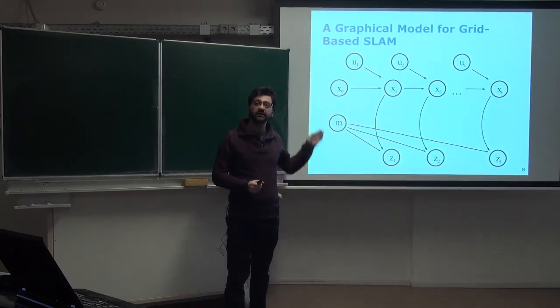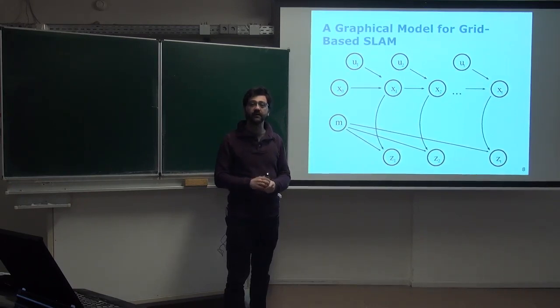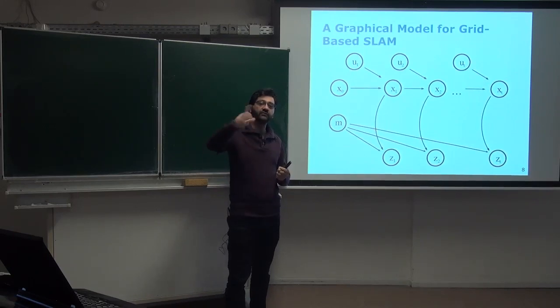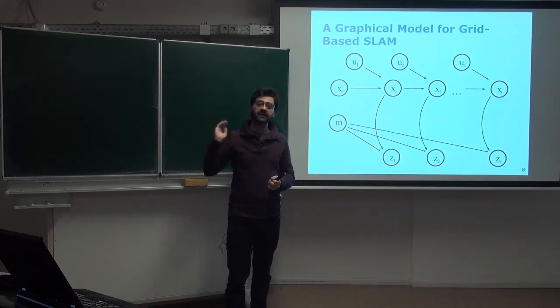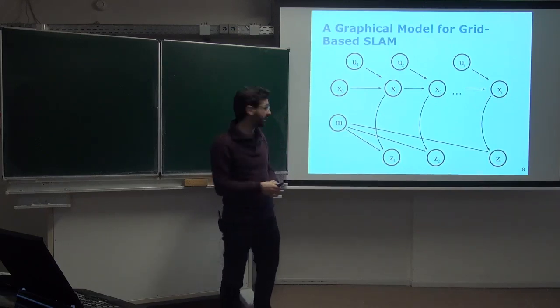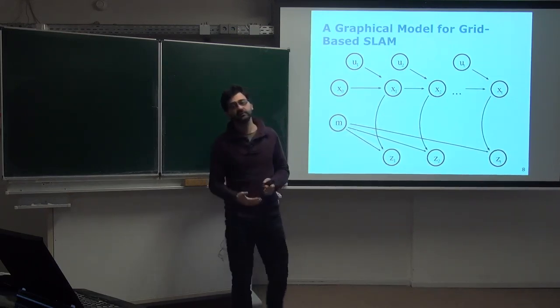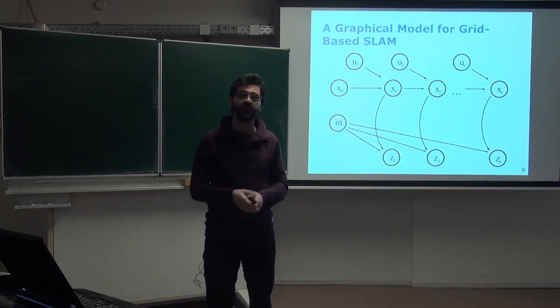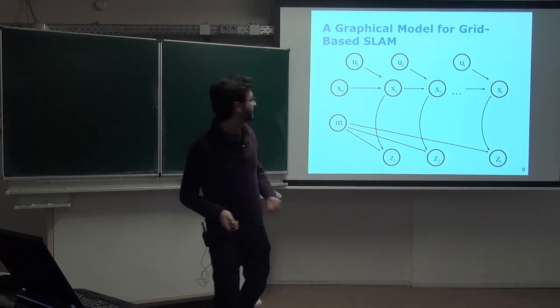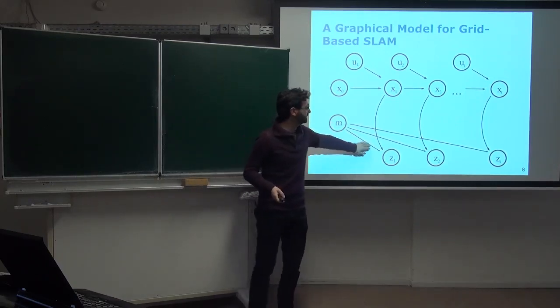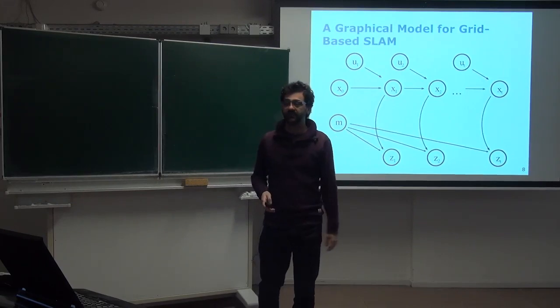Now we have the observation model we've seen, for instance, for the localization problem, where we can do ray tracing on the map and say, okay, this is where my observation should be. Then I take the same beam and compare: the difference between what I expect from the ray tracing and what I obtain is my likelihood, where we put the Gaussian. So that's what we change, the representation and the measurement model.